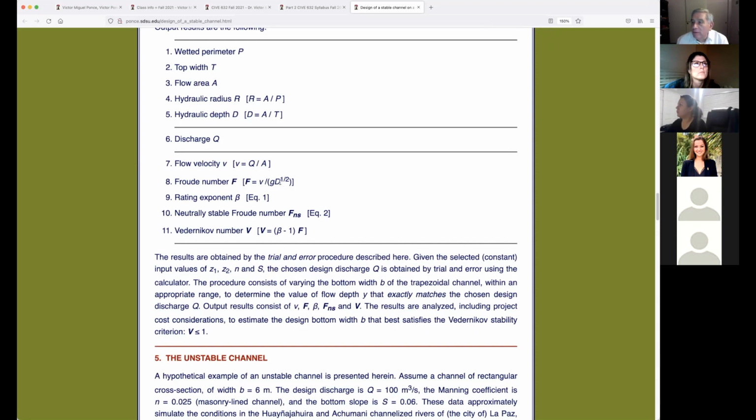And this is where a lot of people make mistakes when they do modeling. They say, oh, the Froude number, Y. Well, no, the Froude number is not Y, it's D. And if they make that mistake, then they're making a 1 or 2% mistake, which of course in engineering is not that big a deal. Engineering does not count on 1 or 2%. But if you're doing modeling, which is not engineering, then you will pay a price. Modeling has to be correct and perfect.